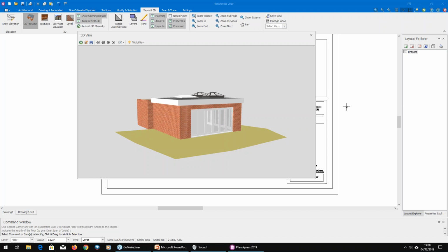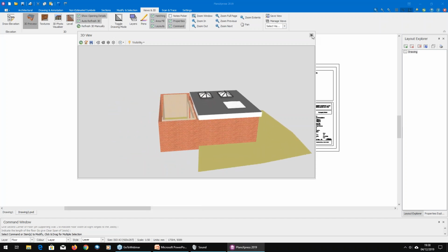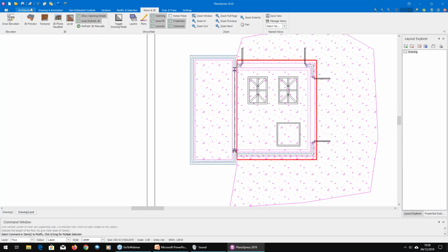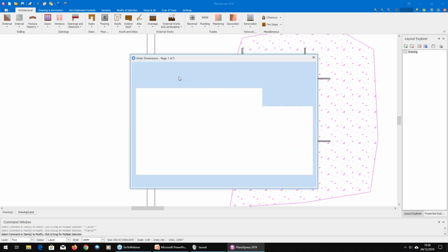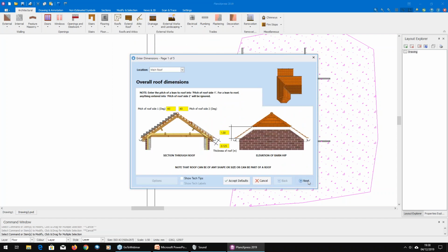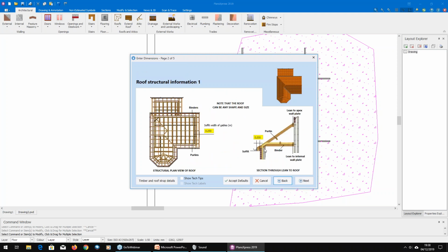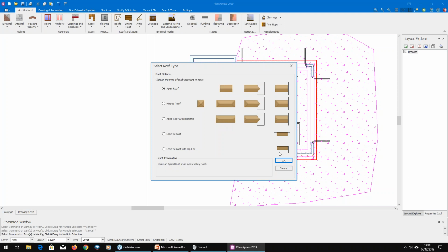So when drawing the roofline, is it the internal skin you work off? When you're drawing the roofline, you can actually click any of the skins of the wall themselves. I use this as an example because it's here. Now, it does work off the internal height of the wall, as far as I am aware from my own testing experience.